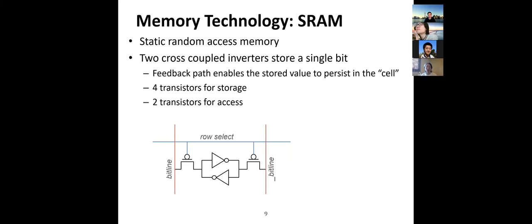And that lower latency makes it an attractive technology to be used for both registers that need to be super fast, as you know, and caches. But just remember that very frequently people associate the layers of the memory hierarchy, which I'm also going to define in this lecture, with this technology. And that's not always correct. Layers of caches like L1, L2, L3 cache, and so on, are not based on the technology. It's based on the logical fundamental organization.